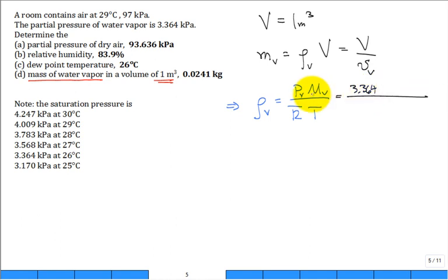And then what about the molar mass of water? Yeah, 18.01 or 18.02, I forget. It's 02? Oh, right, 18.02. And then R bar, 8.314. Units on that are kilopascal meter cubed per kilomole Kelvin. You've used R bar so many years and semesters, it's your old friend. And then the temperature, that's our 29 plus 273. That's our dry bulb temperature in Kelvin. When we do that, we get a value for rho, multiply that value of rho times the volume, which just happens to be 1.